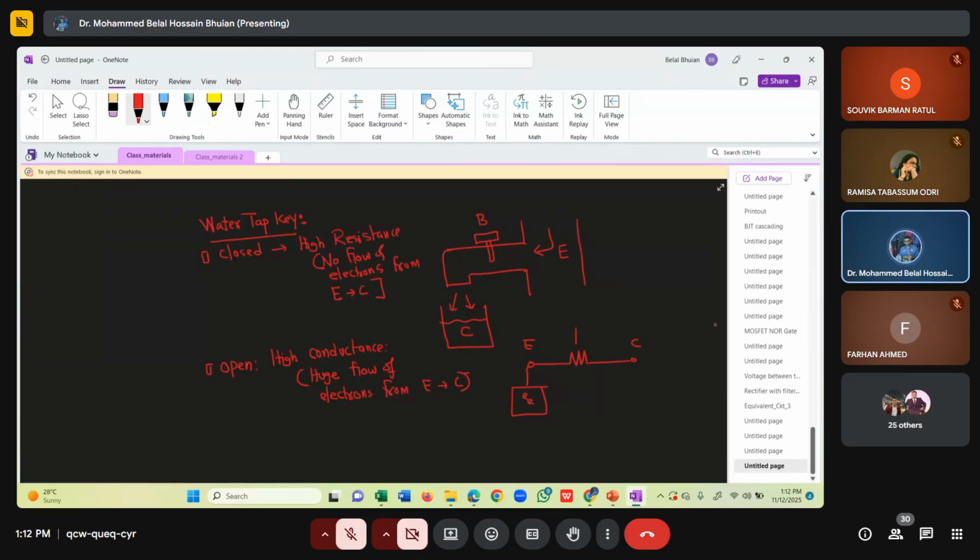If you apply a third terminal, which is the base, you can make it very conductive, or you control the base such that it becomes resistive, no current. We learned the same thing for MOSFET. So in an analogy, the base is very much like the gate of a MOSFET, the emitter is like the source, and the collector is like the drain.